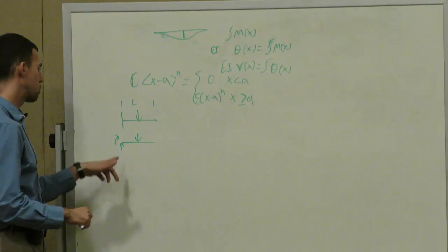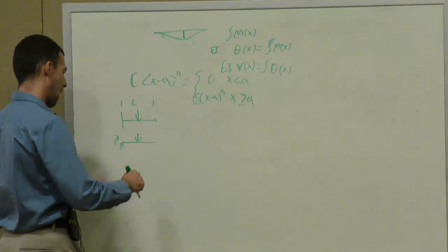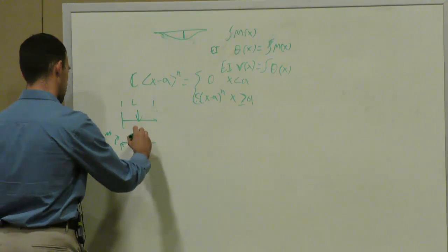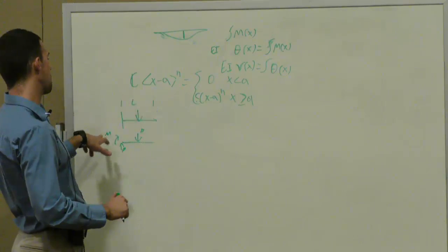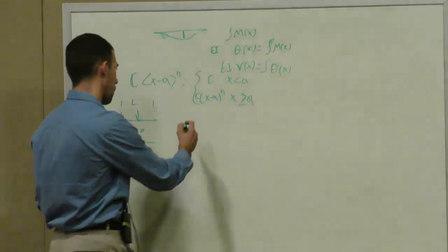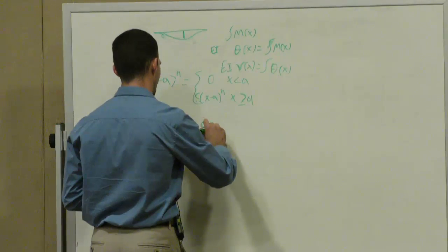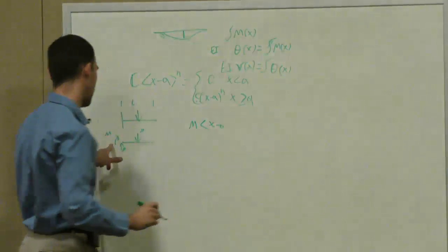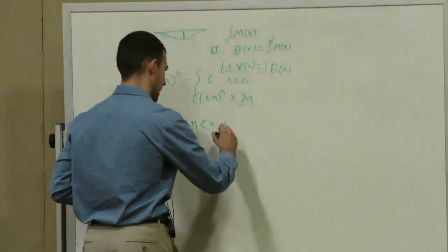So now you start from the left and go to the right. So we have a moment. Let's call the moment M, and let's call the load value P. So what happens is, for a moment, the Macaulay function takes on the form M, whatever the value of the moment is, times x minus a. Our a in this case is 0, because this moment happens at point 0.